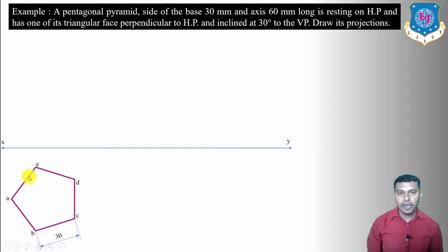As you know that the pyramid has the apex point and the slant edges. So first of all we will try to define the top view of the apex point. To define the apex point, we have to connect this corner to the midpoint of the opposite edge like this, and likewise we take another corner and connect it to the midpoint of the opposite edge like this.